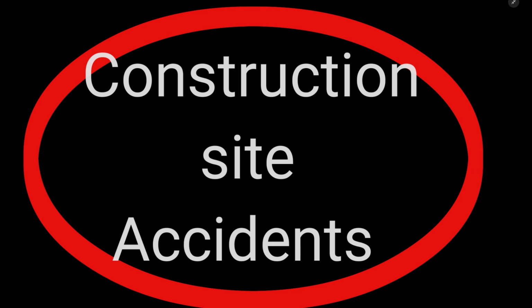Sixth is lifting injuries. Back injuries and strain from lifting heavy loads are common. Proper lifting techniques and the use of mechanical lifting equipment can significantly reduce the risk. Workers should be trained in correct body mechanics and should never lift more than they can safely handle.